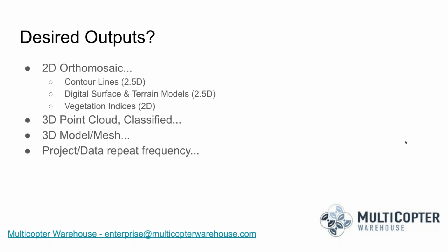Yeah, the Pix4D capture application does fully support swapping batteries mid-mission, but you just want to make sure that you have your fail-safe set properly within the DJI Go or Go 4 application, because Pix4D capture will respect those, and whatever battery fail-safes you've set in those will be reflected on the messages you get from the capture app as well.